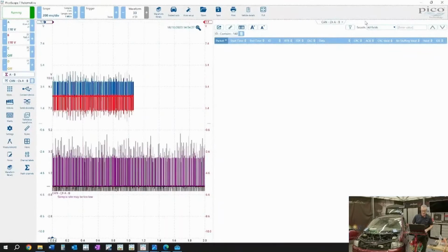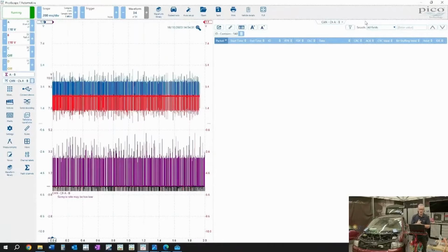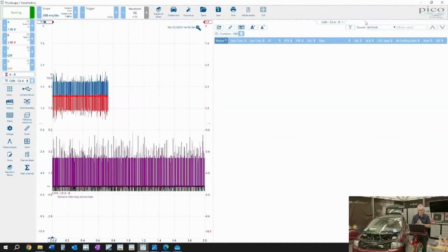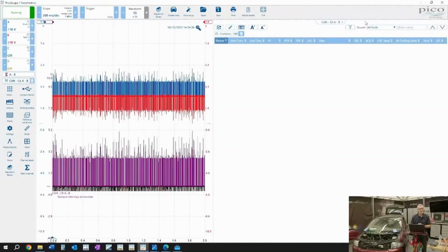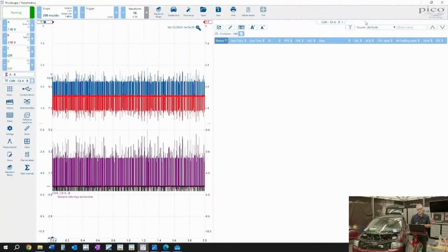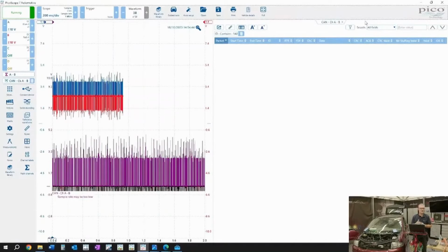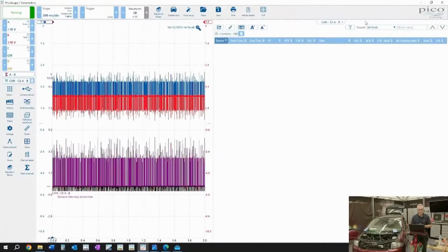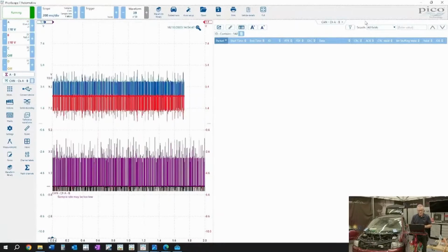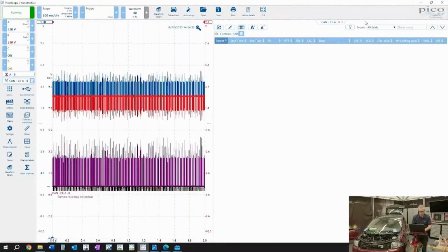Now notice, it's not really that clear on the left, but certainly the bus traffic has dropped off. It seems there's less traffic. But now 1A0 does not appear. There will also be other IDs that don't appear, because not only is 1A0 from the ABS, there will be other ones. I think there's 4A0, 5A0, 6A0. Nevertheless, a quick way of determining whether or not 1A0 is online.